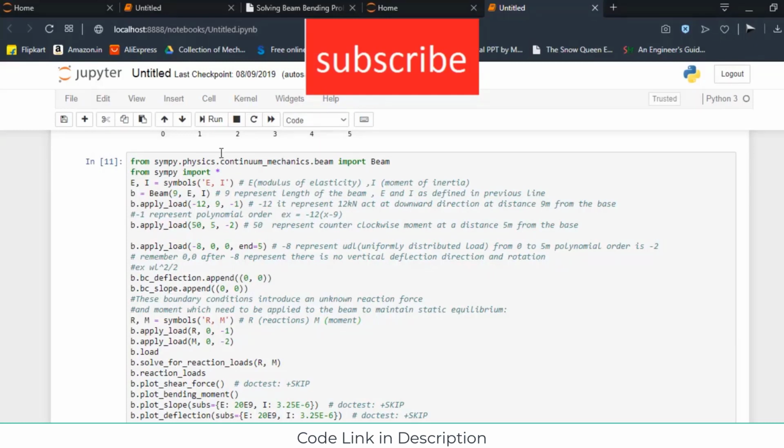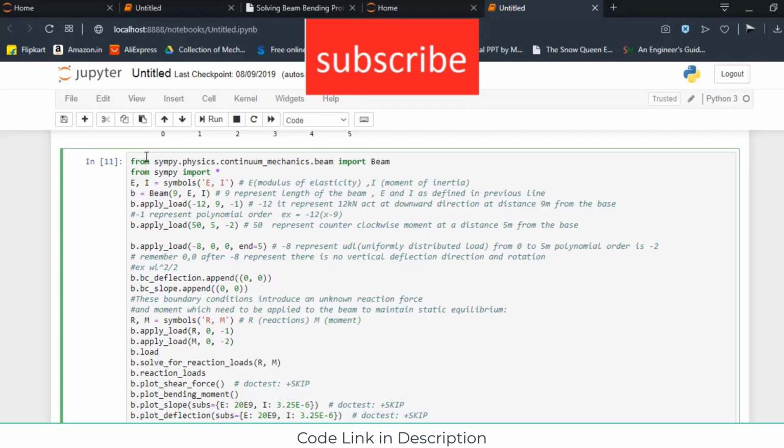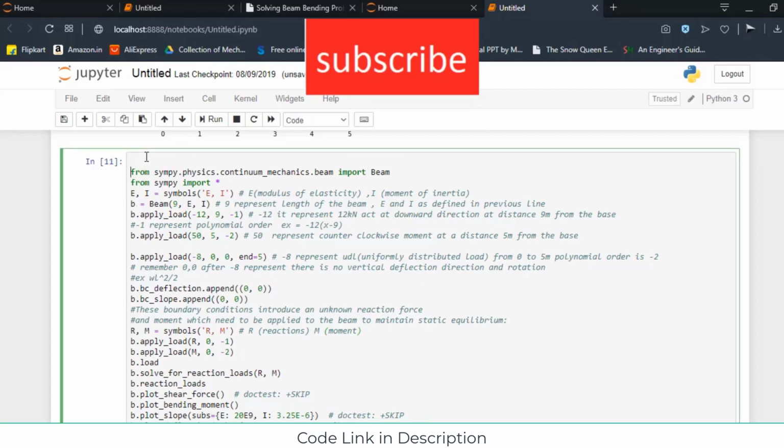First of all, I am using a sympy continuum mechanics module, import beam. This library is specifically designed for plotting shear force, bending moment, deflection and slope. So make sure you install this. You just need to run pip install sympy. If you don't know how, you can simply go to your CMD and type pip install sympy, and it will install automatically, and after that you can use this code.